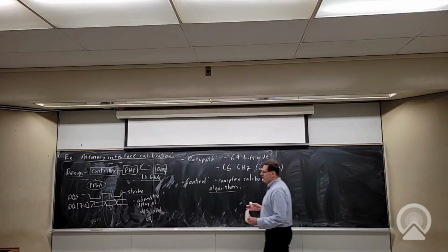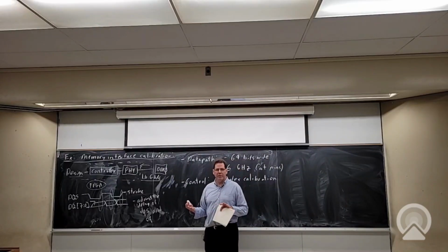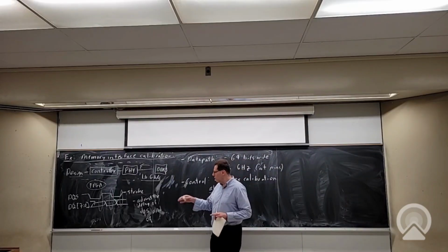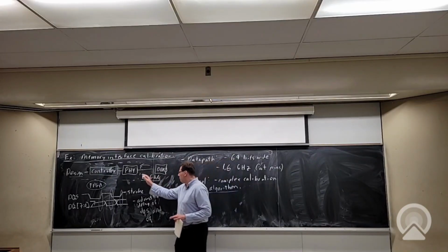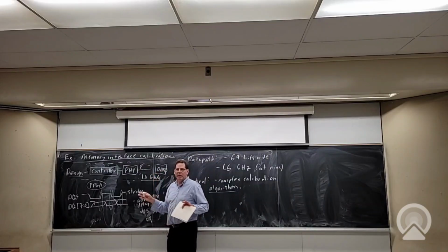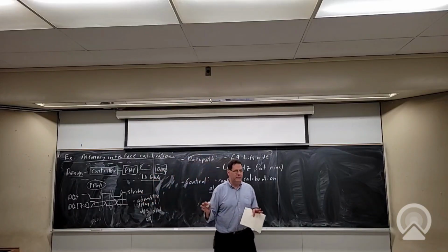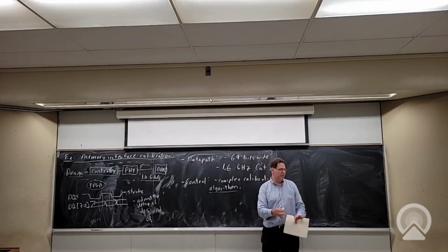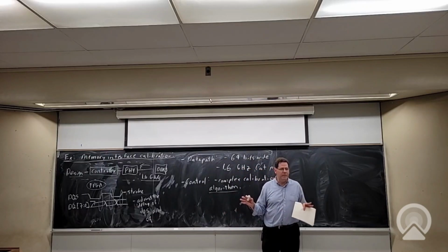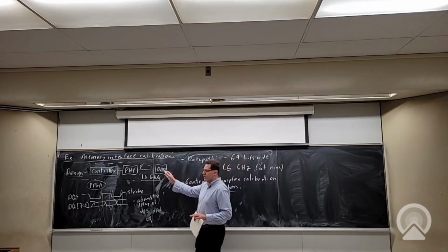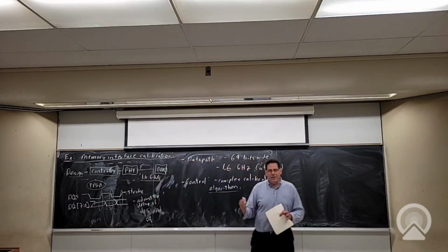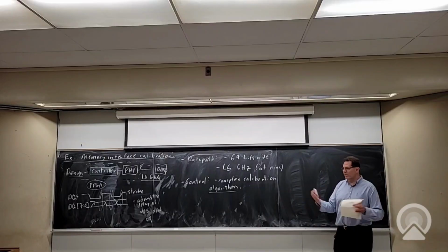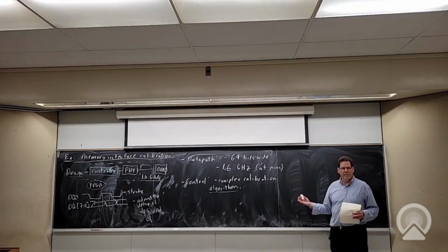Once it's calibrated, so when you actually turn on an FPGA, if you have a DDR IP core in it, it will calibrate without you knowing. Part of the chip powering up is it will calibrate to the RAM, and only when it's calibrated will it start accepting read and write commands from you. So there is some relatively short period where it won't listen to you. It's calibrating in that time. But how do you organize this? We've talked about a bunch of compute models. What do you think we should do to make this work?